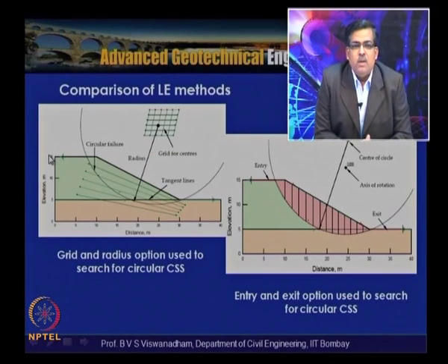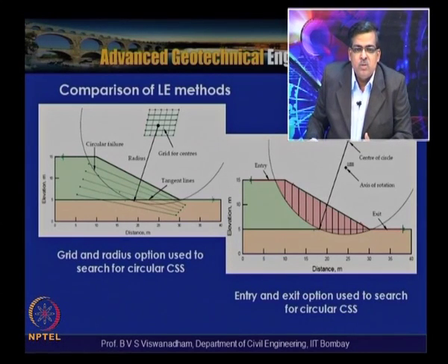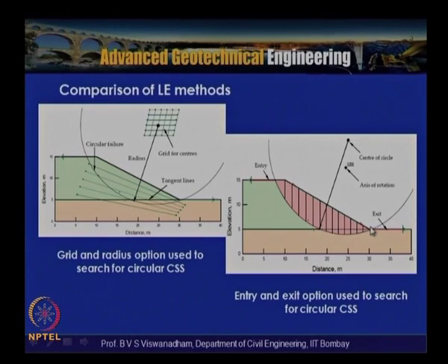However, some limit equilibrium methods are done through softwares like GeoStudio, wherein Slope/W takes a grid of centers and also gives the possible tangent lines. It sets the circles within this grid with the tangent lines, with prescribed intercepts at the top and near the toe, and with the grid of centers it tries a number of circles. The one which gives the least factor of safety is evolved as the critical failure surface, and this is called the entry point, and this is called the exit point.